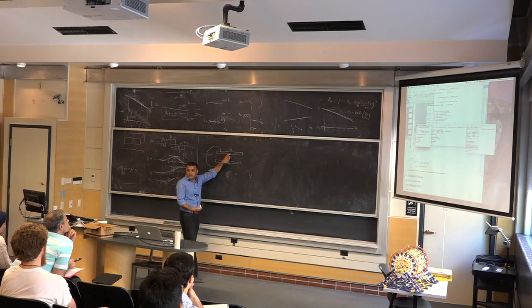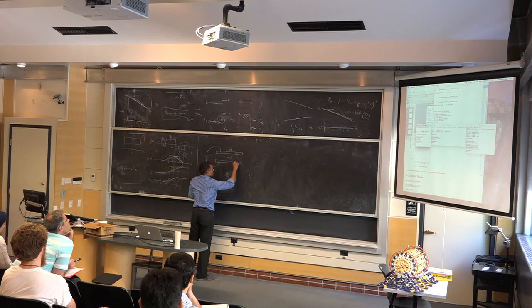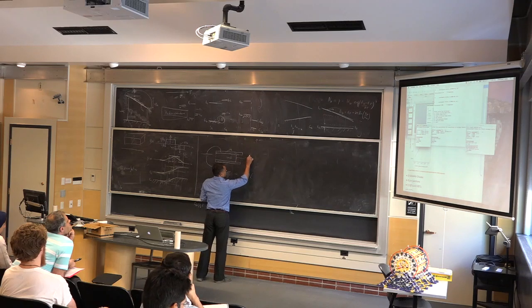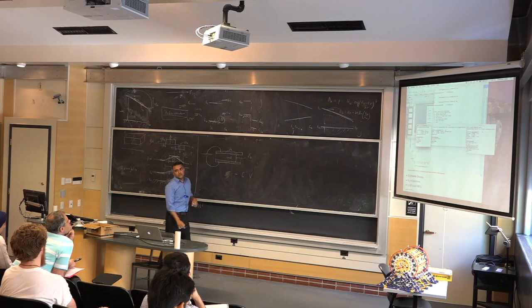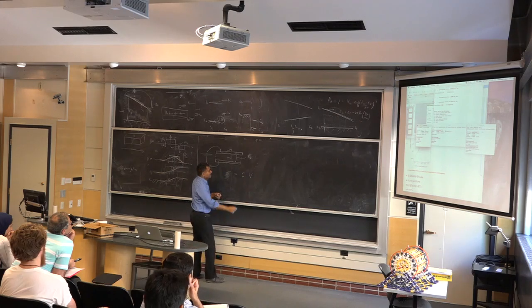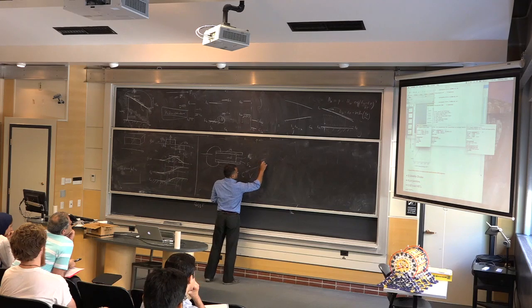Yeah. So there's no trick in that. It's a very simple capacitor. So what's the charge? That's right. So essentially the answer is it is just the capacitance times voltage, right? And what is the capacitance? If you know the insulator material, let's call it a barrier, with dielectric constant epsilon b and thickness d_b, then the capacitance happens to be the dielectric constant over the thickness.